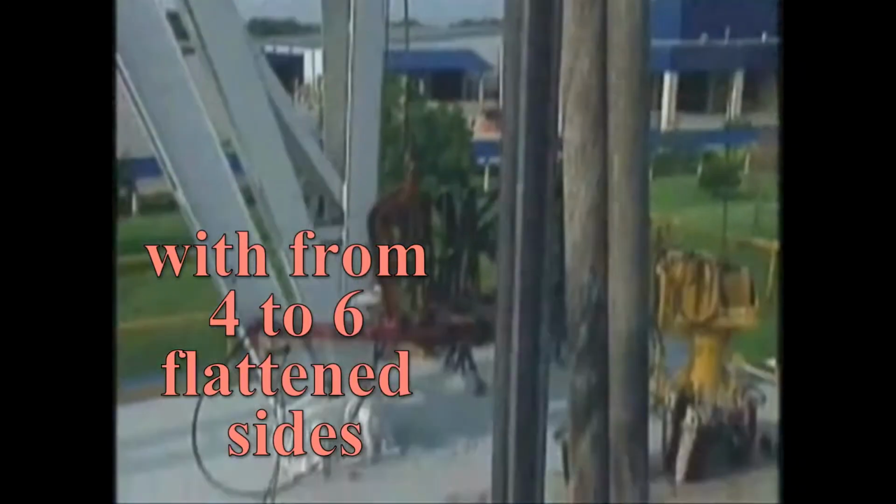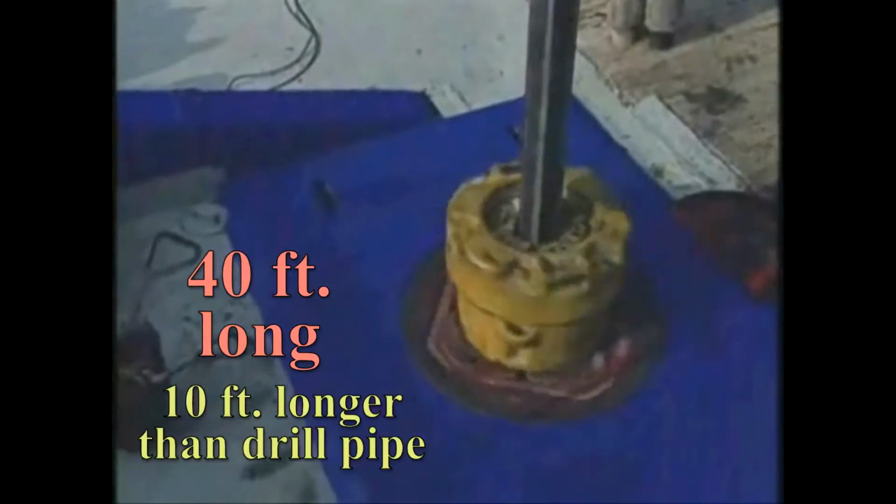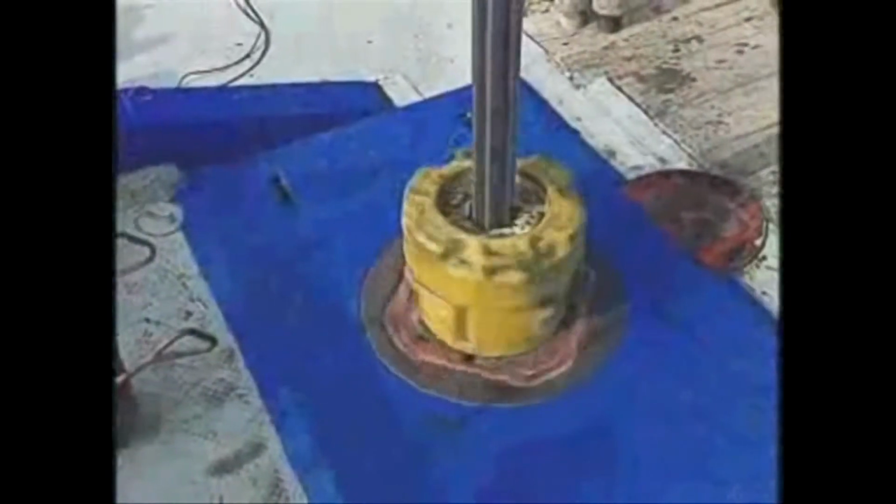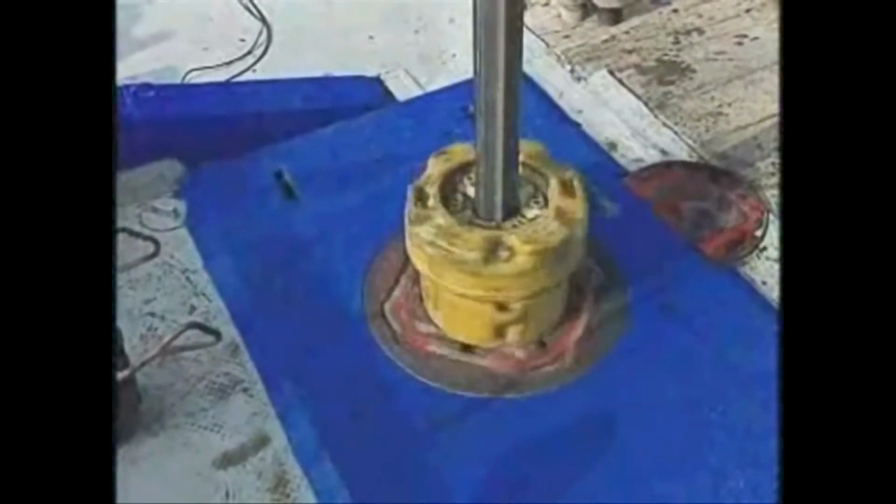The Kelly pipe is the topmost joint of the drill string with from 4 to 6 flattened sides and is 40 feet long, 10 feet longer than drill pipe. The Kelly or top drive transfers the torque, or rotating power, down the drill string to the bit, allowing the rock to be cut.